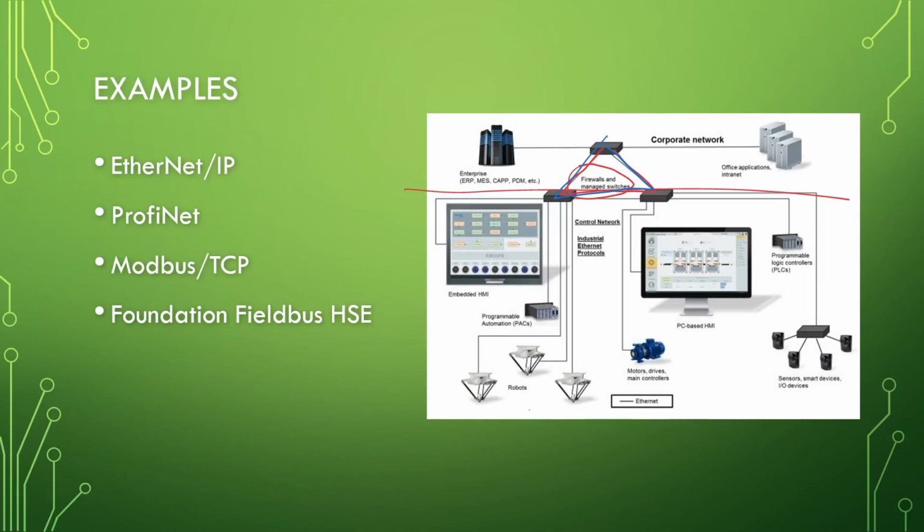Profinet is actually an evolution from Profibus, which again is Siemens communications. So they've kind of modified it. Oftentimes, a lot of these industrial protocols are modifying serial communication to the Ethernet standard in some way. So we had to change basically the cable, the media, how we're connected, but most of the protocols that are actually being sent, the messages and things, haven't changed. It's more of just going from serial to Ethernet. We're using that hardware for the Ethernet, but we're still using the same types of messages. Alrighty.